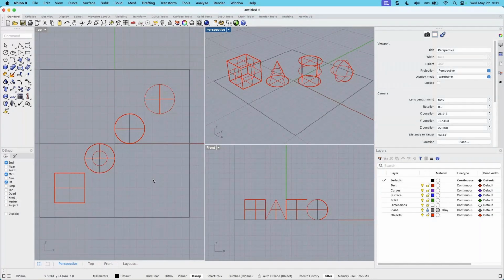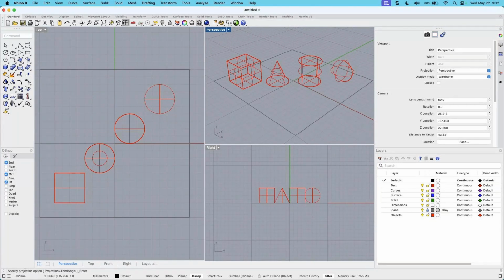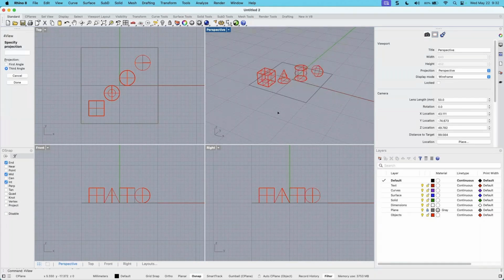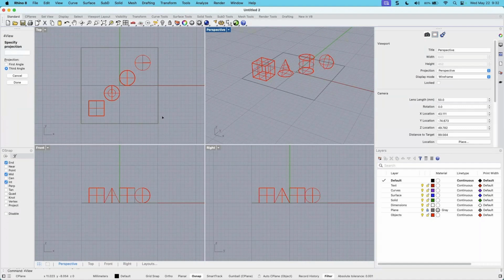So start.3dm opens, and it opens in this 3 viewport mode. So what I would like you to do is either type in 4view or pick the 4view command up here on the standard toolbar. And you can also pick it down here to return to 4view display. So like I said, you can type in 4view and return this model to the 4view display. And let's look at navigating around this model.